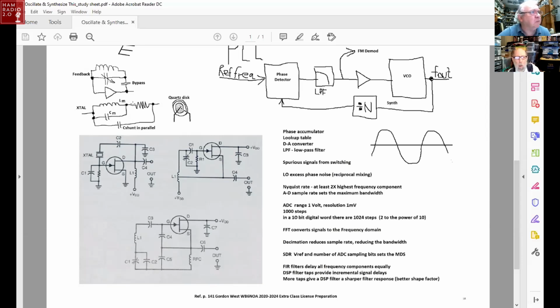It also has a resistance in series, which is a loss. Any resistance that you run electric current through produces a loss. There's also a capacitor in parallel. It's called a shunt capacitor, and that is the packaging capacitance that's in parallel and connected to the two leads coming out of the crystal. See, the two lines coming off the crystal model are the two leads as represented in my attempt at this drawing of the quartz disc.